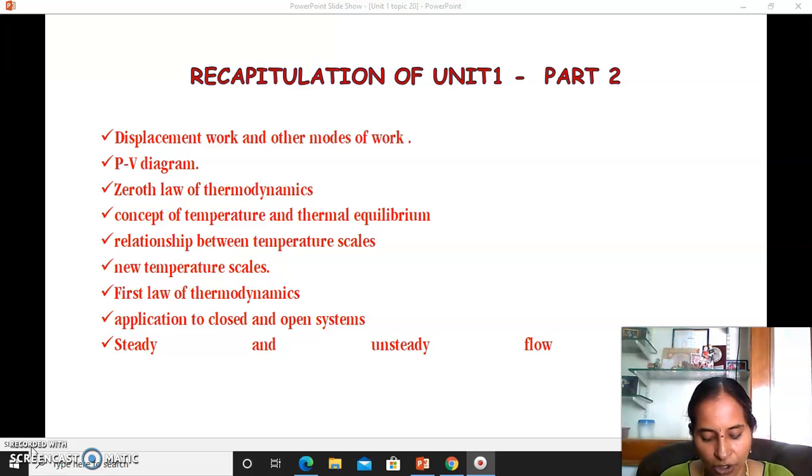Okay, the major characteristics of free expansion are that it is unresisted, unrestrained or irreversible, and no work is done during the free expansion. For an isochoric process there is no work done, and for an isobaric process the work done equation refers to P integration of dV. An isothermal process gives you P1 V1 ln of V2 by V1, and for adiabatic and polytropic processes you have (P1 V1 minus P2 V2) by (gamma minus 1) or (n minus 1).